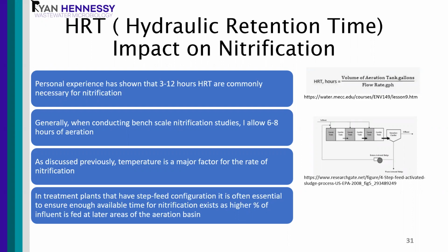So hydraulic retention time also has an impact on nitrification. From personal experience, when we run nitrification bench studies, generally anywhere between 3 to 12 hours of HRT are needed for nitrification, and that's at a bench scale, kind of simulating what your mixed liquor concentration would be in a plug flow or SBR type reactor.